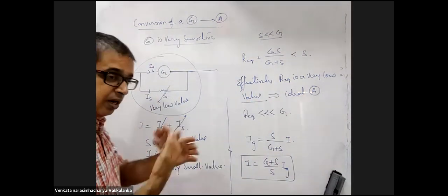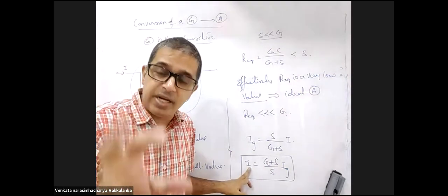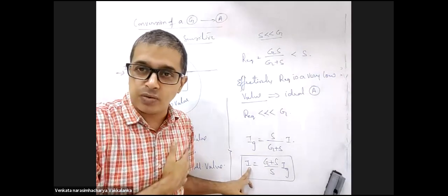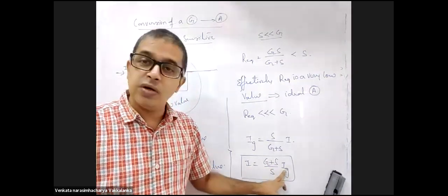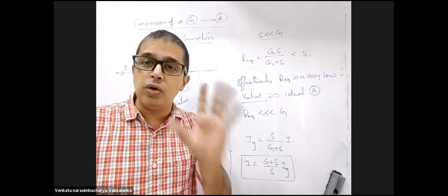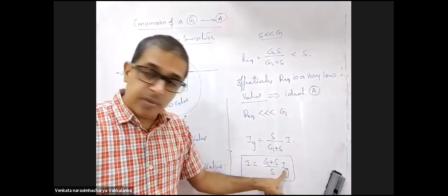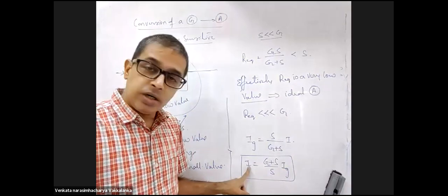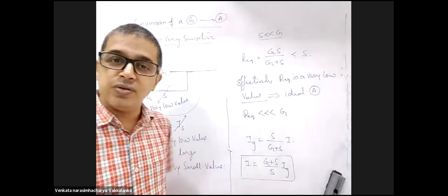So generally they ask the question in the reverse. If I should construct an ammeter which measures up to 10 amperes, what should be the shunt resistance? If the galvanometer can measure only 1/100th of an ampere. Galvanometer takes 1/100 ampere, total 10 amperes, G is known. You are asked to calculate S.